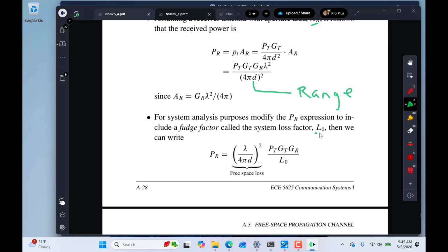It's saying we don't want to have loss, but we know we're going to have some loss in our aperture antennas. What's an idea in your mind about why an antenna would not be perfect, would be loss-free? Just think physics. You build a parabolic dish, and it's supposed to focus in one direction, but you're going to have imperfections in the surface, right? It's not going to be a perfectly smooth parabola. And then the materials and other things. So that's where the LO comes in, something to represent some physical approximation to loss.